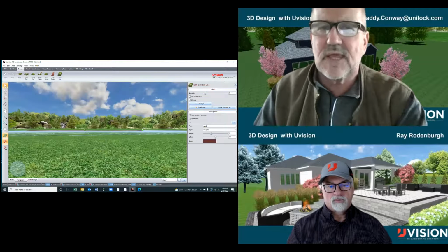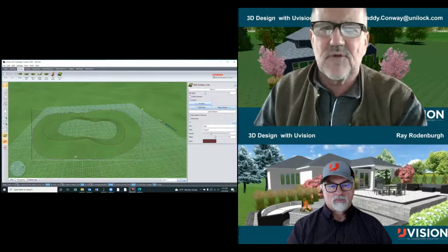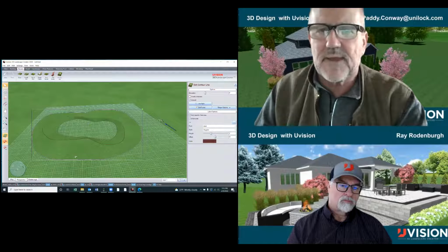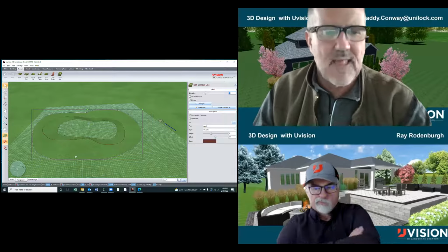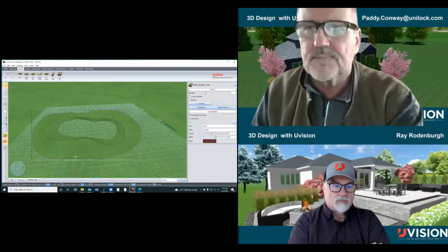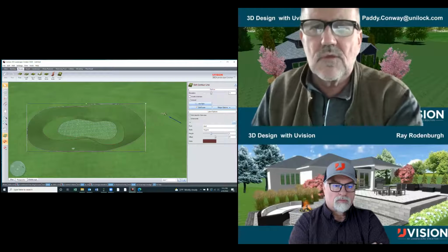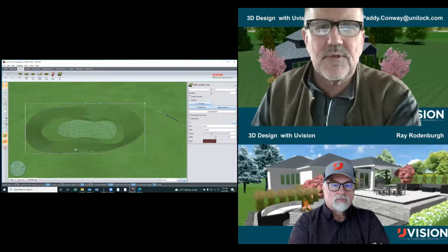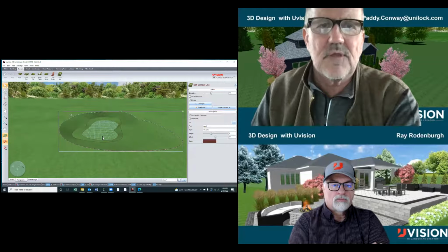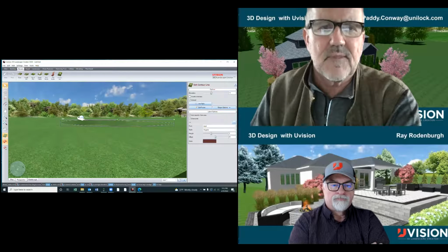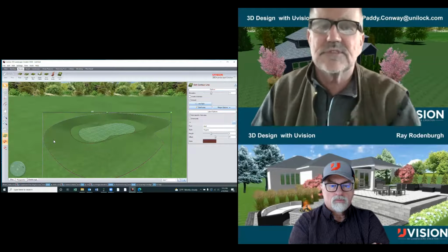I'm going to now put in another one just to show you a drastic climb. And I'm going to make this one. You see, because I didn't designate it, it always comes in at 0. Because I didn't designate anything, you can see the grid back in play. And it's saying we went from 0, climbed, sloped back down here. But once I put this in at 15 feet, you can see now what's happened. I've got 0, 3, 15. And that's what Contours does.